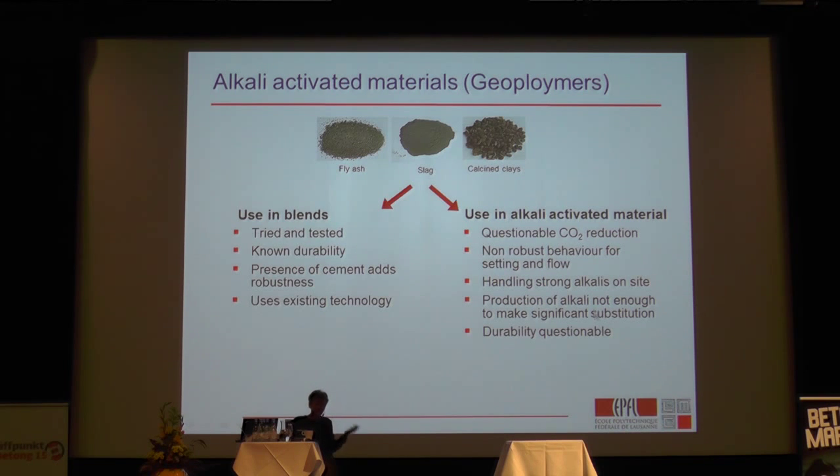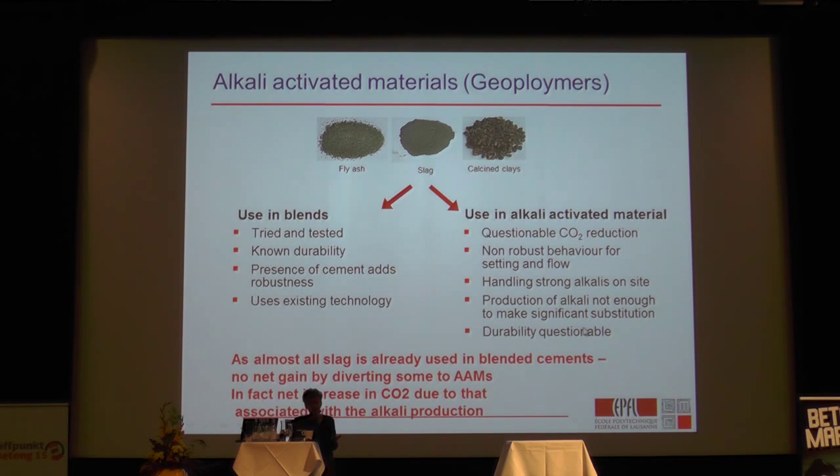And even if you did choose to make alkali-activated materials, because the only one that really works at room temperature is slag, and because all of that slag is already used in blended cements, you're not actually going to be helping CO2 reduction at all.